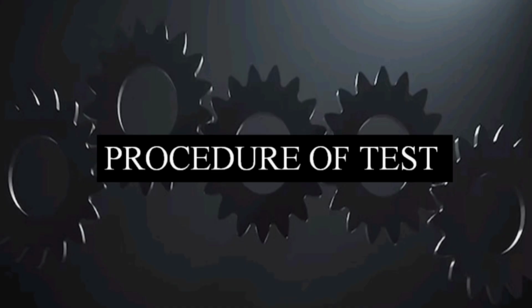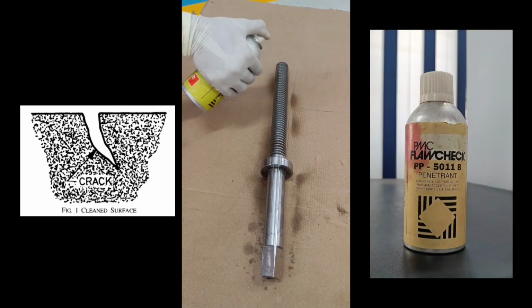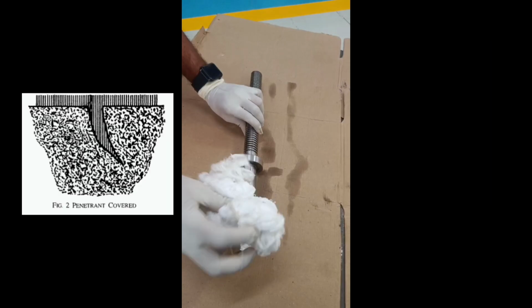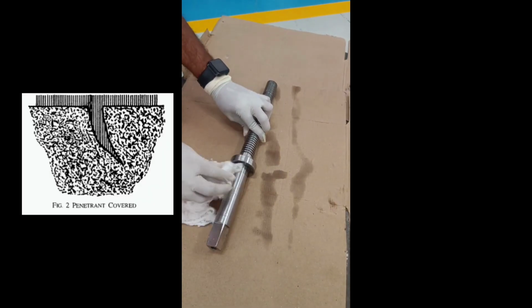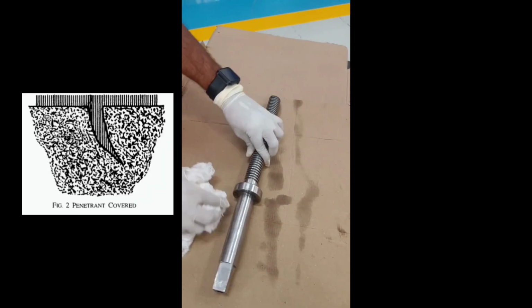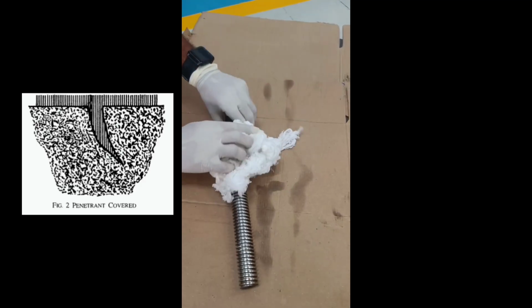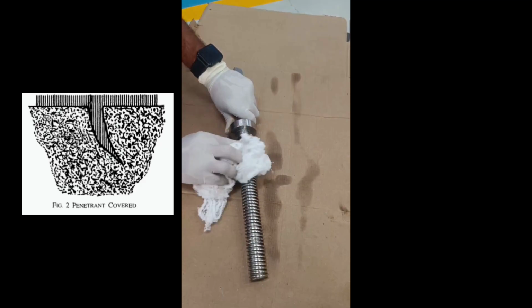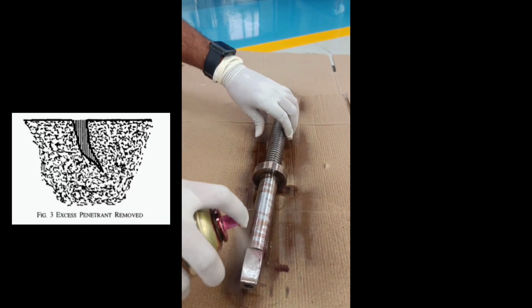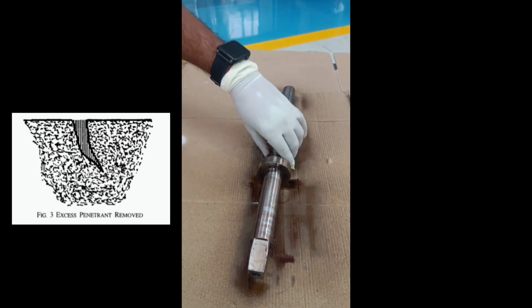Procedure of test. A suitable liquid penetrant is applied to the surface of the component under examination and permitted to remain there for sufficient time to allow the liquid to penetrate into any defects open at the surface. After the penetrant time, the excess penetrant which remains on the surface is removed.